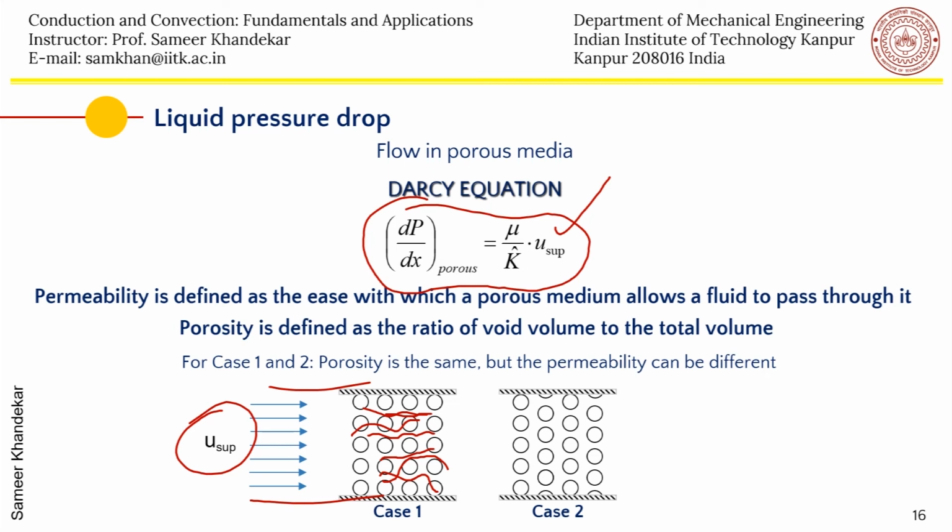So what this essentially defines is that the capital K, or kappa, is the permeability of the medium. As we have seen in the case of screen meshes, this was done easily by geometry, but in many other cases like sintered wicks or other geometries, K probably has to be determined experimentally, but there is enough data available in the literature.